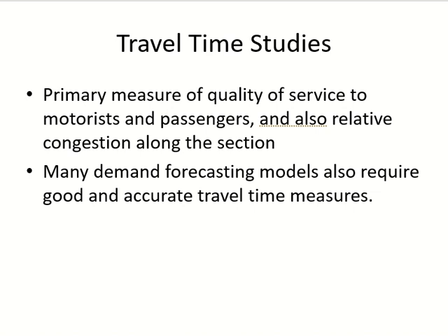You are asking me how do we calculate the demand, right? And I gave you the planning perspective. In long-term planning, the demand is calculated using population and activities. But in short term, for traffic management, if I want to calculate the demand of a highway, I will use travel time in my equations. Okay? Got it? Clear? And you can see the relationship. Travel time is lower, demand will be higher. More people will go towards that highway which has lower travel time.